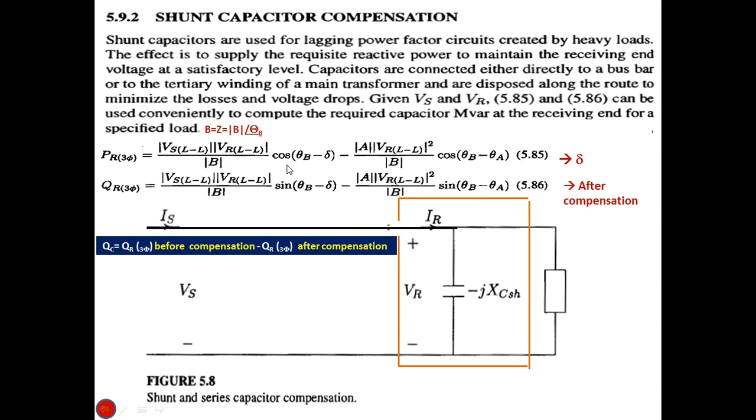Here we will be calculating the angle delta first using equation 5.85. And then, thanks to delta, we calculate the reactive power after compensation.